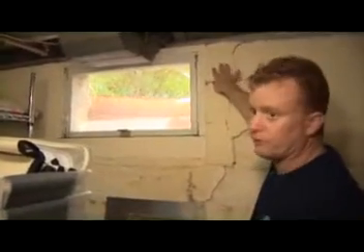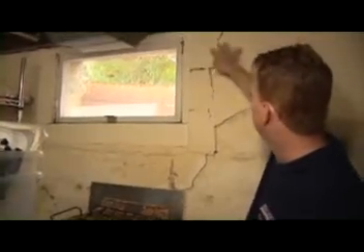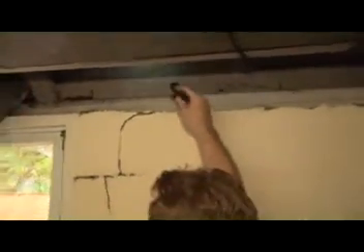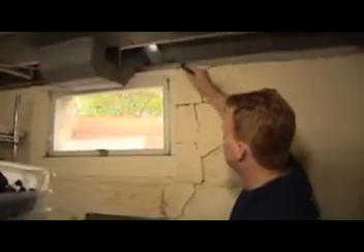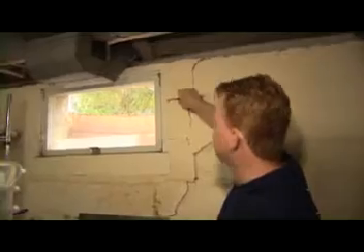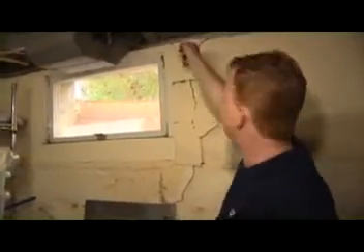We have air flow coming from the foundation. So these cracks in the foundation here, we could feel a nice amount of airflow. This is the rim joist here, this band of wood that sits on the foundation wall. You have right angles when they construct the house, and those are generally poorly sealed. So one of the more common measures to seal your basement is to insulate that rim joist all the way around the perimeter, and that'll generally be done when it's accessible with a 2-part foam that they'll just spray there and seal it up nice and tight.